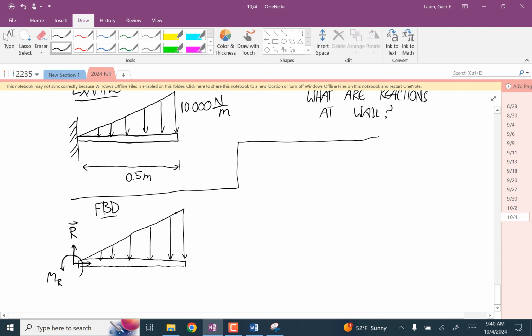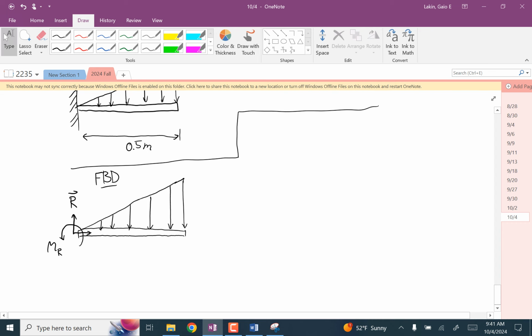And now that we've chosen the body to isolate, we can represent. So the thing is, once you choose the body to isolate, you're always treating your free body as a rigid body. Okay, that's true in deformable body mechanics too. Everything. So we've chosen the body to isolate. Now we can represent this as a point force. So let's think of the distributed load shape.